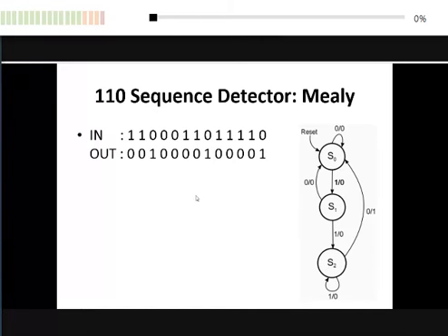For me, normally I do it that way. Seldom do I analyze straight from the input-output and build the Mealy model. I have done that before, but I had a miserable time doing it. So that's why I prefer to convert from the Moore model state diagram to the Mealy model.